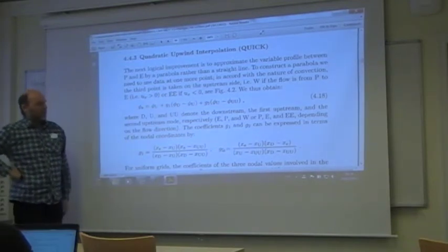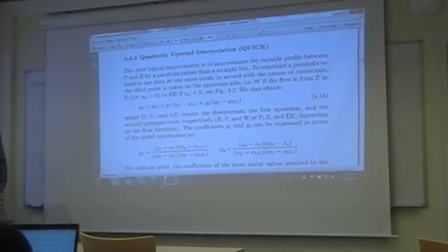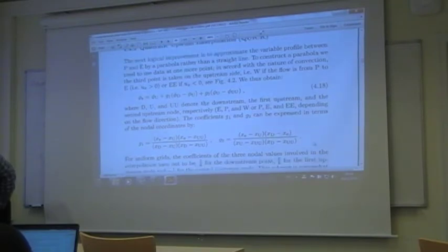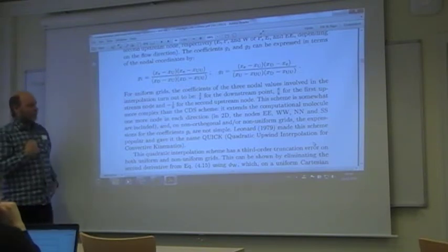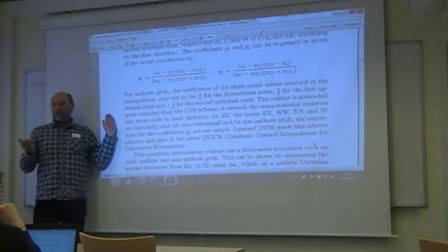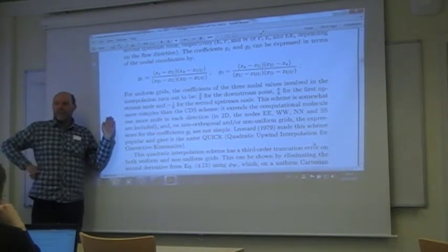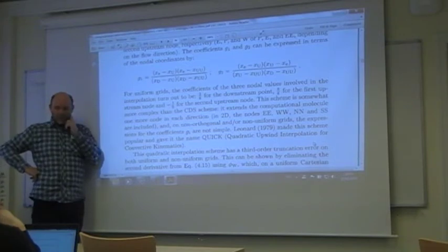So then this one will be better than the first order upwind. It's second order accurate, but it's still an upwind scheme, still involves additional viscosity into your problem. So QUICK, you use it with care. That's my advice. And typically what you will do in practice, if you have a problem, you start out with the first order upwind. It's very stable, so you should rapidly get a solution, which is wrong, but you get it.